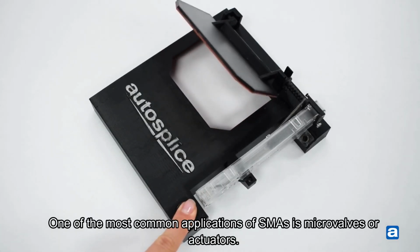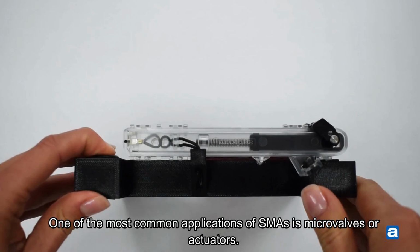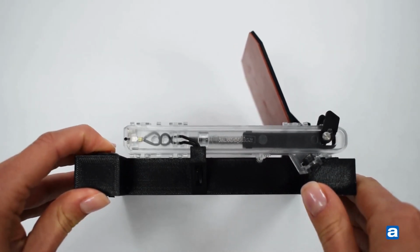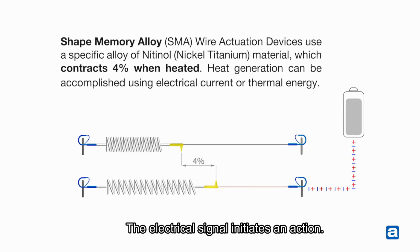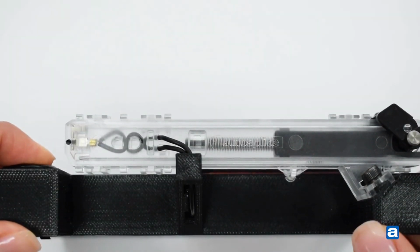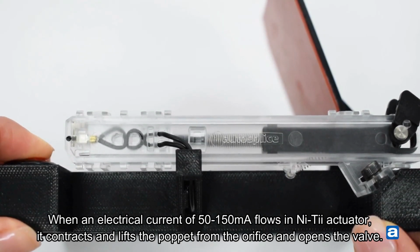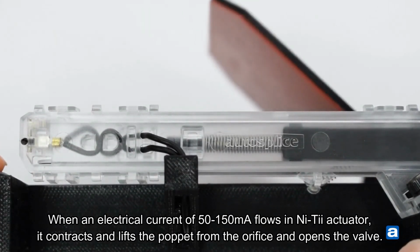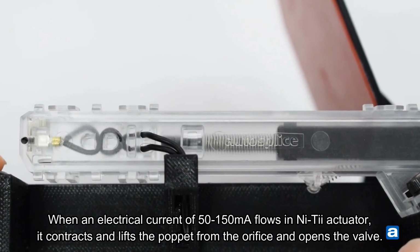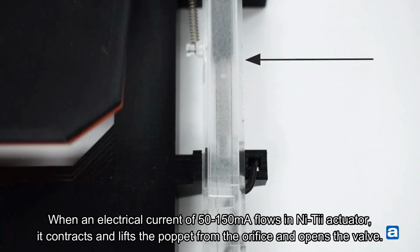One of the applications is the microvalve. One of the most common applications of shape memory alloy is the microvalve or actuator. The electrical signal initiates an action. When an electrical current of 50 to 150 milliampere flows in a nitinol actuator, it contracts and lifts the poppet from the orifice and opens the valve.